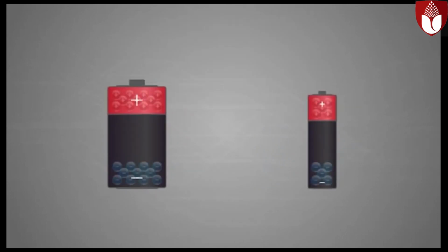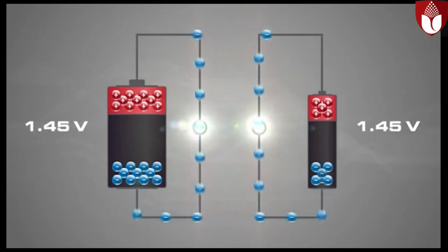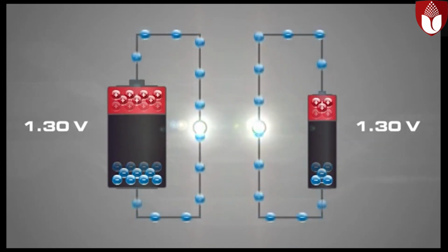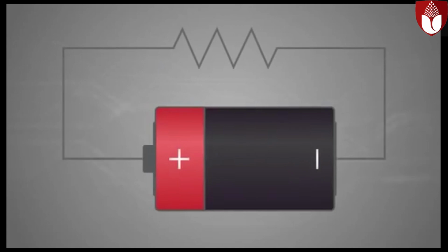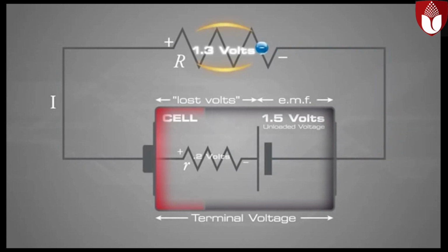The potential difference across two open terminals is known as the unloaded voltage. The electrical potential difference forces current flow when a circuit is attached to the source of EMF. There is typically some amount of resistance in all electrical components and devices. When current flows, the voltage across the terminals of the source of EMF is no longer the unloaded voltage value. There will be a voltage drop inside the device due to the internal resistance of the EMF source.